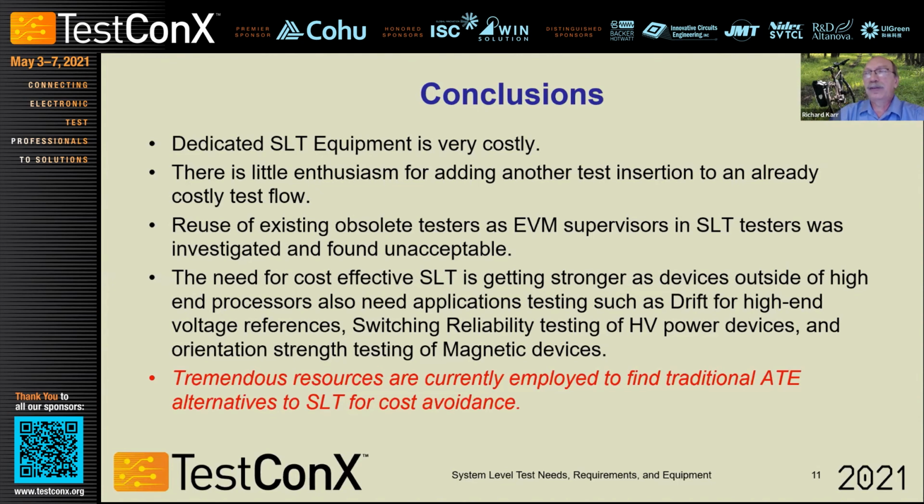It's one thing to have thermal heads that can ramp from room temp to high temp, right? That becomes a much easier task than moving the temperature of the die from room temp down to cold temps. And from our survey, it shows that there's even a significant challenge going from like 0C down to minus 40C.